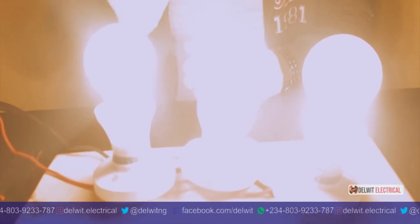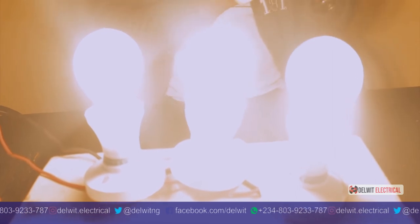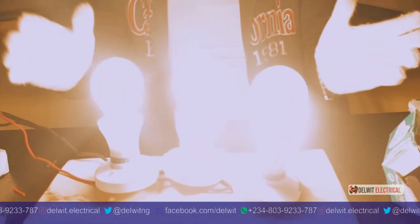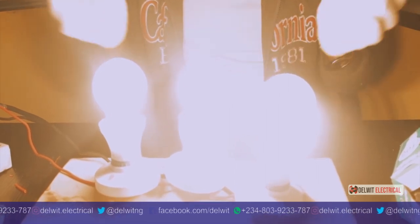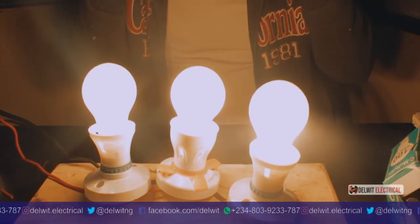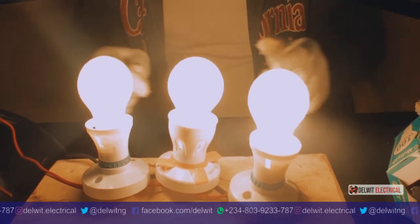You can see that the voltage here is equivalent to the voltage here, is equivalent to the voltage here. If you had looked at our last week lecture, you will discover that the voltage here for the series is less than the voltage here, is less than the voltage here. But this is parallel connection. You can see that the voltage level is the same. So that's parallel connection. This same principle is applicable to all other parallel connections. So when you are doing your calculation, what comes to your mind is voltage in parallel is the same, while current changes. So I believe this topic we've treated, resistors in parallel, has been very educative.